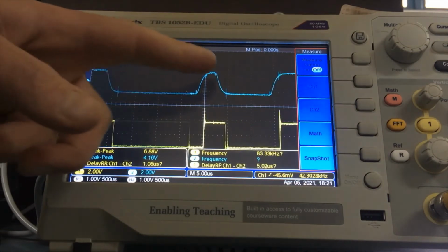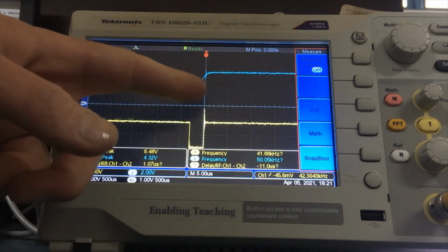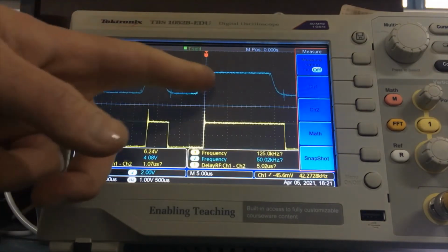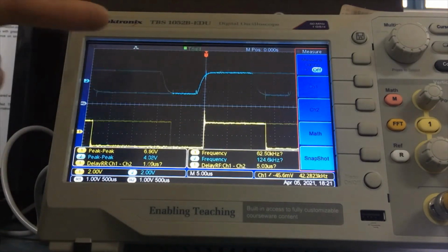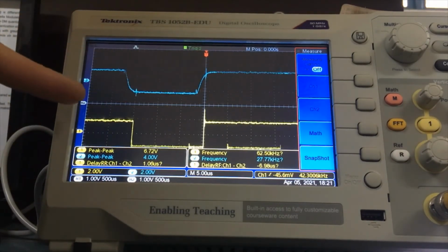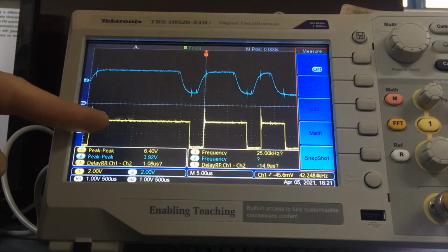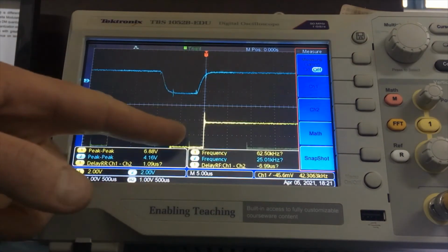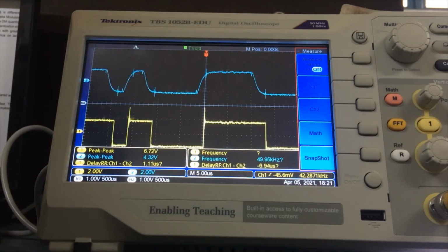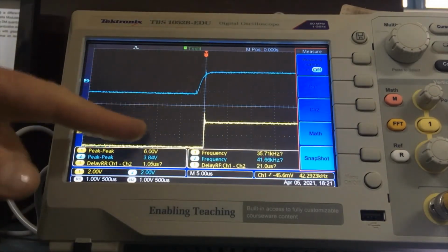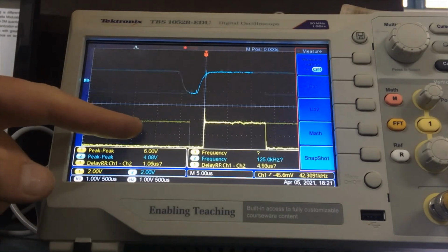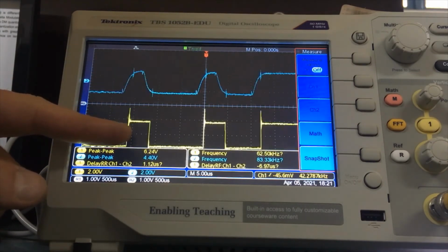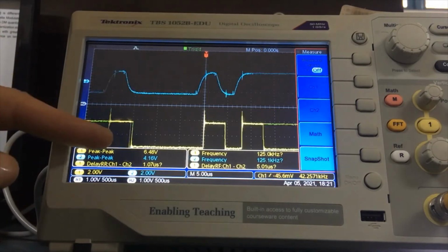We see the higher frequencies being removed at the received signal, but they need to be restored again. So we pass this signal through the clock and data recovery stage, which restores the high frequency elements. You can see a perfect ones and zeros square wave appearing over here, and this recovered PCM signal would now be passed through the pulse code demodulator.